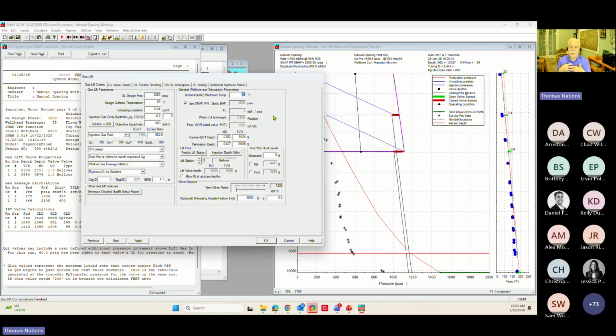For example, my basement here in Denver is about 10 feet deep, and the average temperature year-round, summer and winter, is roughly 60 degrees all the time. So that's the number we're talking about here when we talk about ambient wellhead temperature. It's the earth temperature at roughly 10 feet. And that's where our tubulars and the hot fluids flowing up them are going to be losing temperature to the earth at the top of the well.